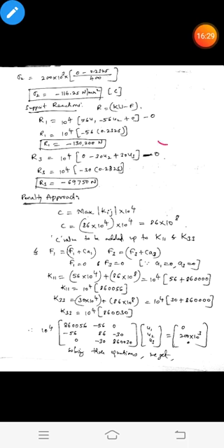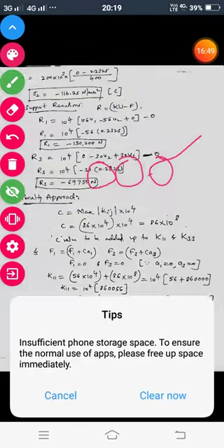Next, R3, considering equation number 3 of the overall equilibrium equation, we got 10 raised to 4 into 0 into U1 minus 30 into U2 plus 30 into U3, minus F3, that is Ku minus F. F3 we have as 0.